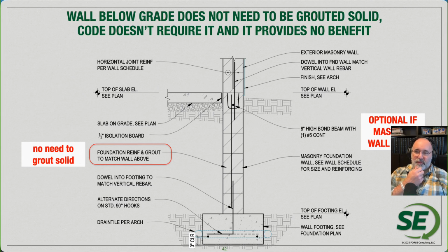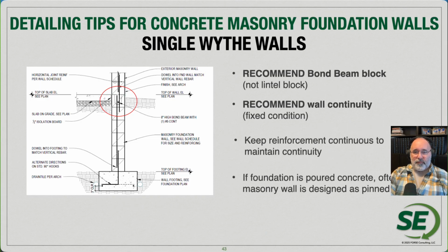So again, you have the ability to get to grade, stop construction, and have a dowel that's going to be exposed in that design. Having the bond beam there gives you the ability to transition at that point. But again, having good site conditions, the soil sloping away from the site, and drain tile and all of that is going to be important for the design.